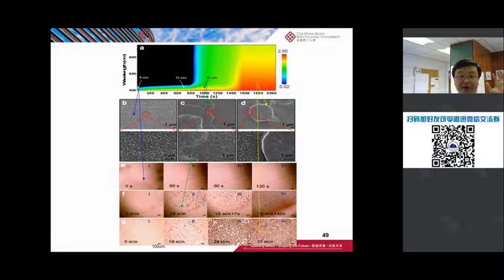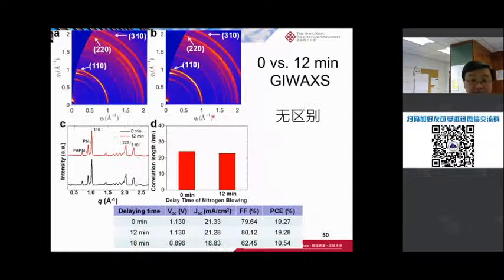You start to have some perovskite aggregates already, but if at that time you start to do air knife quenching, you basically can lock it. You will see the perovskite big chunks there, but the other part will be fine. So that's an intermediate phase. No more words about that one.